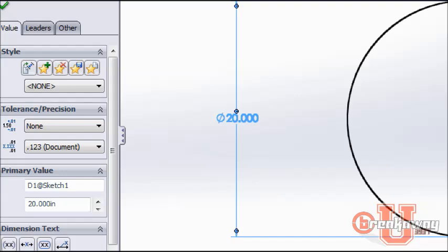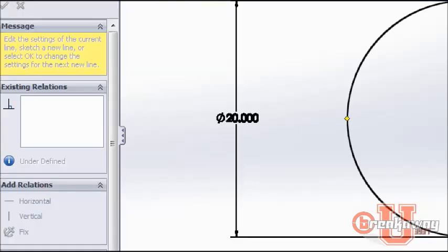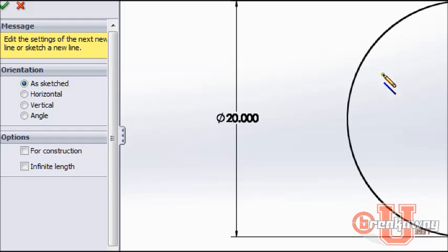Let's look at a line. And let's take that line from perfectly above that circle, and go right through the origin. See the mates or the relations that are appearing there. The relation here, at the end of my eraser, means coincident and vertical. And I'll go through the bottom. Snap twos, I love them. And notice I'm still dragging. I don't want it, so I'm just going to double click and it'll go away. So now I've got a circle with a line drawn directly through the middle.